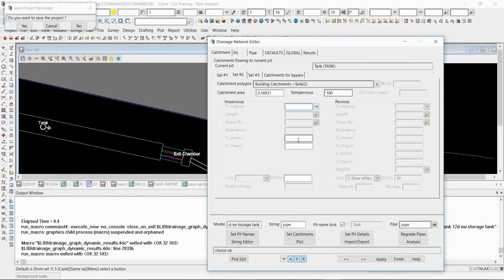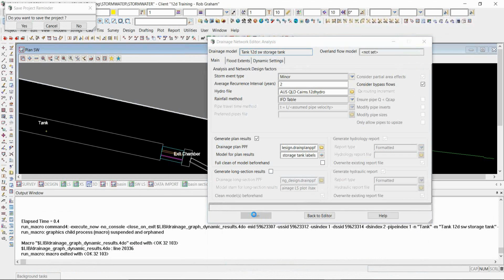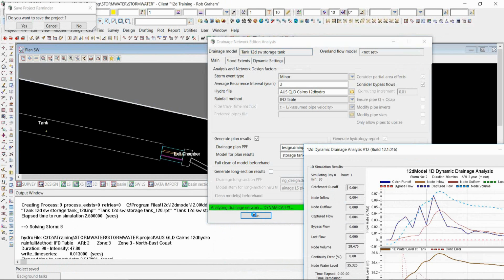So the flows are going to change much more rapidly with the changes in rainfall. The second thing is the storage that we'll have is going to be much smaller on the impervious areas. So I'm going to put that down to 2 millimeters. So now that we have this post-development hydrology in, let's go back and rerun that. So I'm going to return to my analysis tab and go run that 2-year once again. Only this time, of course, we're going to be using the new hydrology.